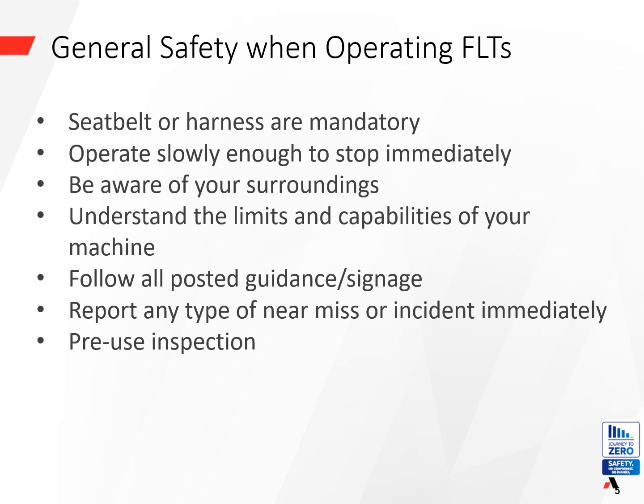Seatbelt or harness usage is mandatory at all times. Operate the forklift at a speed that allows you to stop immediately if necessary. Stay vigilant and aware of your surroundings at all times. Understand the limits and capabilities of your machine and operate within these parameters. Adhere to all posted guidance and signage within the workplace. Report any near misses or incidents immediately to the appropriate personnel. Conduct a pre-use inspection of the forklift before each operation to ensure it is in proper working condition.